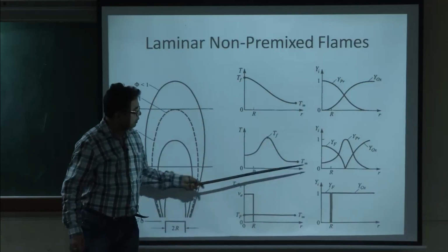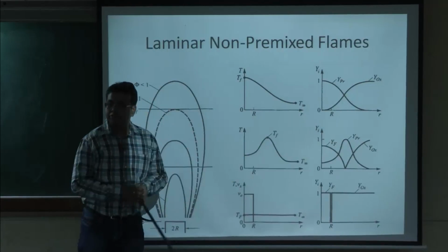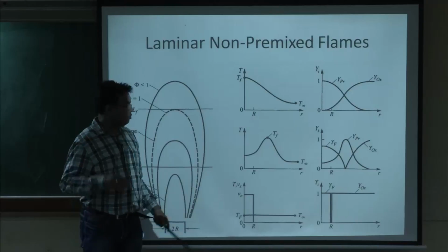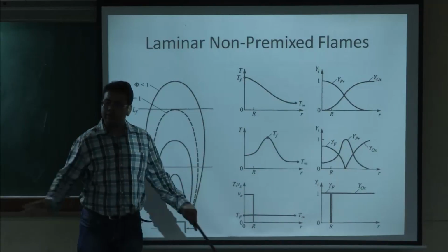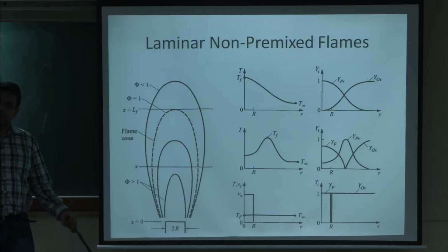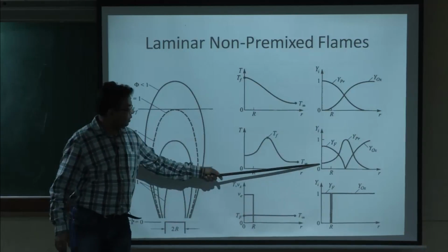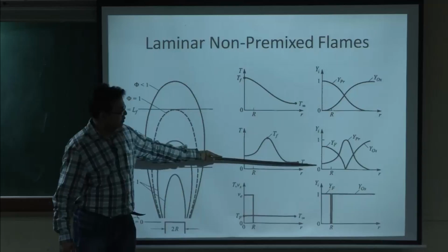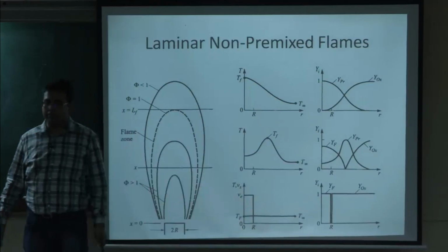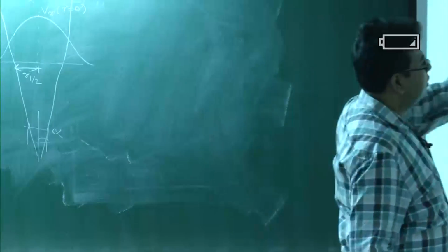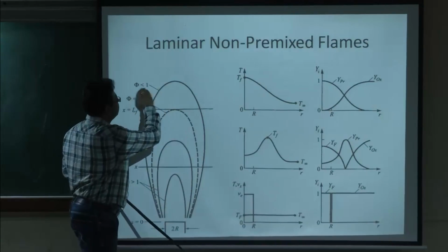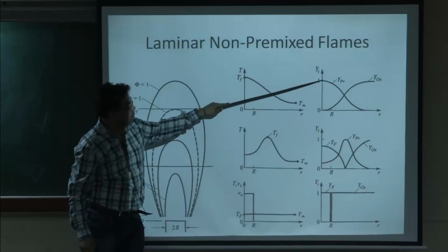Another important thing is that when you are forming the product, the product is getting diffused on either side of the flame. Okay. So, product will form at the stoichiometric location and it will diffuse to both the lean and the rich side. I mean both through the oxidizer and the fuel side. Okay. And if you go on further downstream, then the center line concentration of the product will gradually increase until it reaches the maximum here. Okay. And beyond this, the product mass fraction will gradually decay. Okay. Beyond this, if you plot here or here, it will not remain like 1, it will gradually decay.